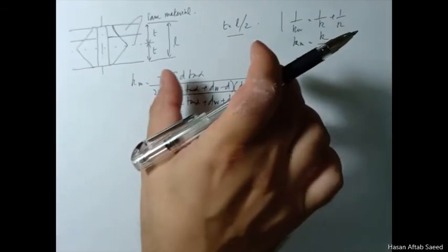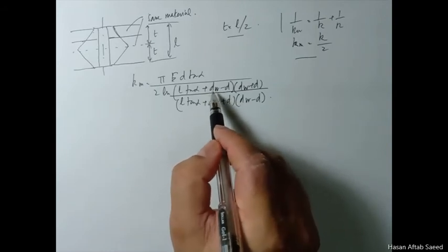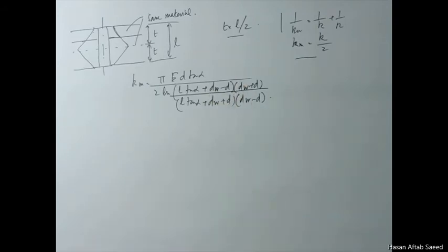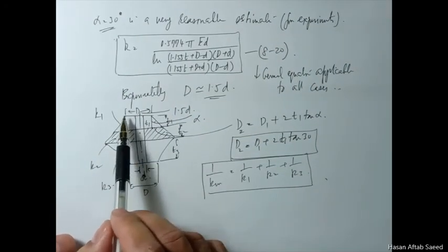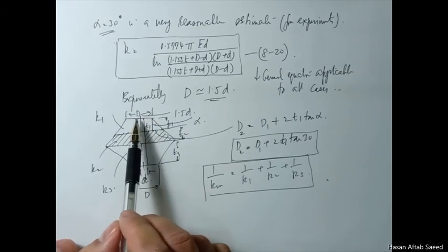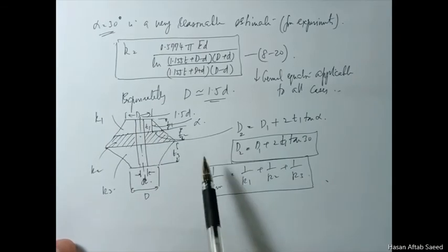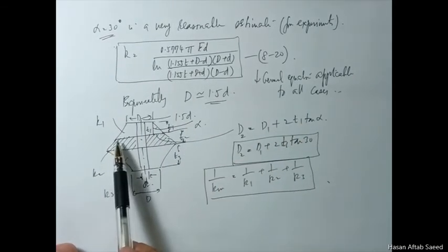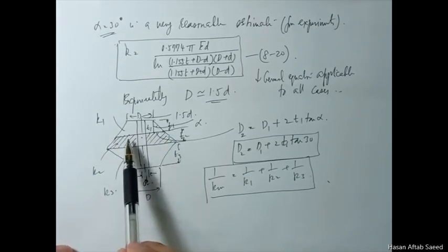Now you can see that dW has replaced the big D here. That is because in the general case, sometimes you'll have this diameter here, and in that case it's called washer diameter, because the washer is placed here, dW. But the same formula is applicable for this second frustrum also, and there this D is not washer diameter, this is much bigger than the washer diameter.